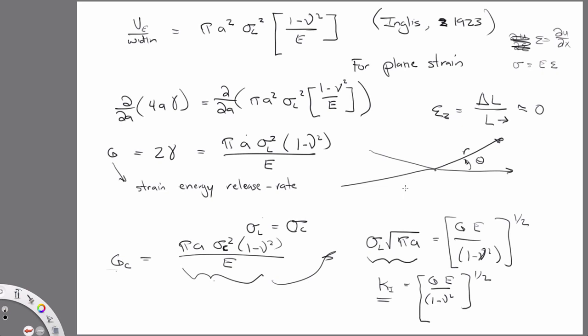No material can withstand actually infinite stress. So there's sort of a hole in the theory of elasticity at the tip of a crack. And so fracture mechanics was invented to fill that hole. The way it works is that you solve asymptotic solutions, okay? And all of the information about the stress at the crack is contained in this stress intensity factor.